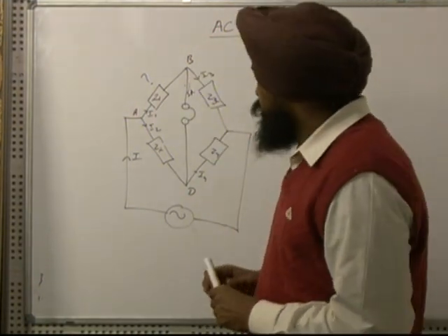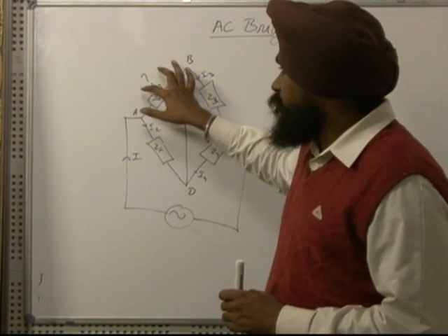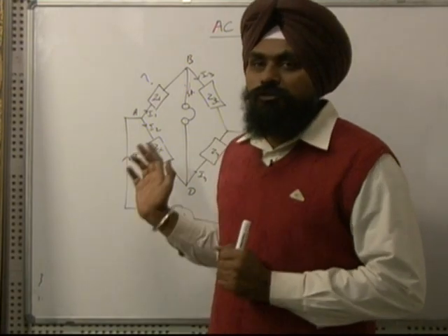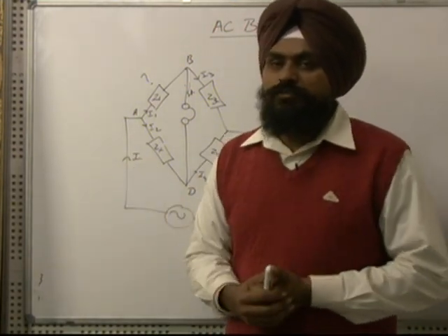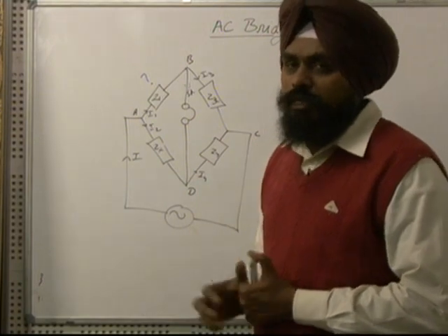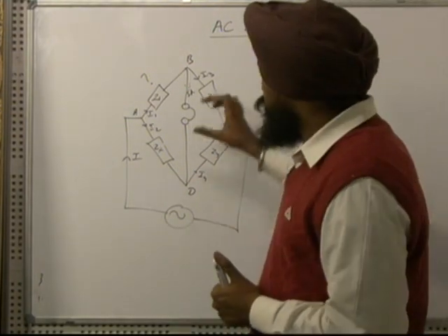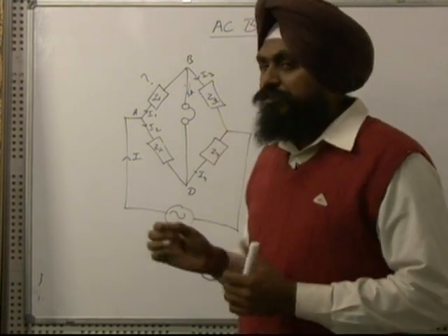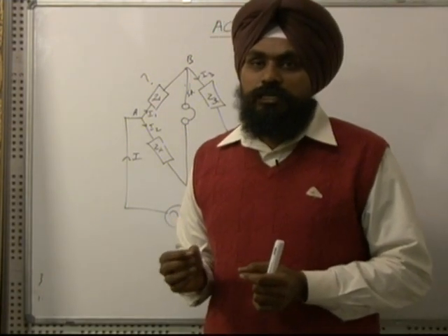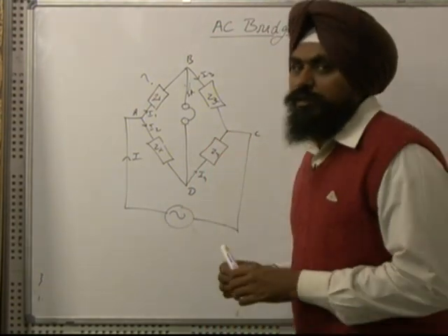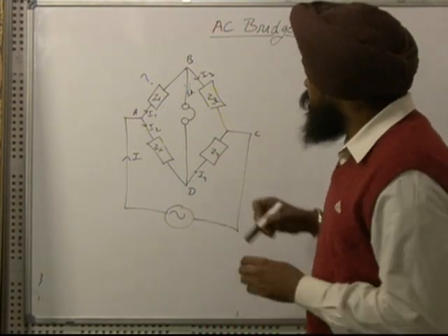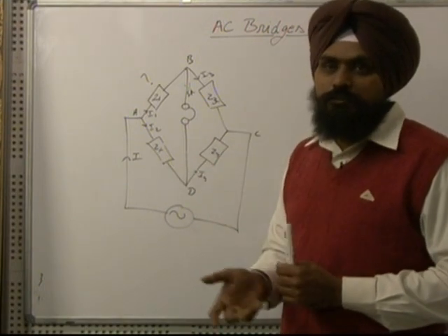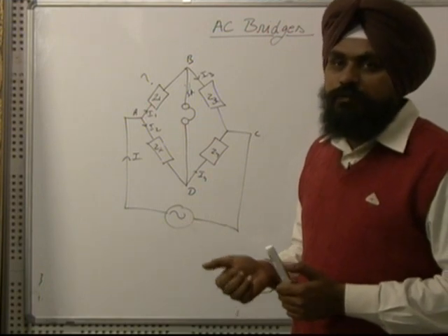Now what we do is we vary. जिस टाइम पे आप वो impedance लगाएंगे तो इस डिटेक्टर की आर्म के अंदर जो हमने हेडफोन लगा रखा है, that we will discuss afterwards कि why we had connected headphone या क्या क्या हम कनेक्ट कर सकते हैं. So we had connected a headphone. So the current flowing through this headphone will produce a sound. Humming sound आपको सुनेगा, and जब तक वो साउंड कम नहीं हो जाता we will vary Z2, Z4 और Z3. There will be some variable terms जिनको आप वेरी करेंगे, जिन इम्पिडेंस को वेरी करेंगे.